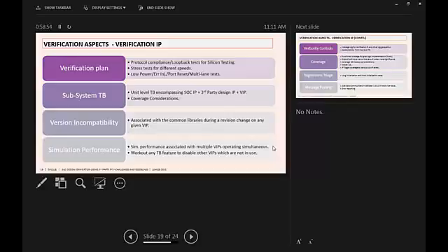When you get verification components from the same vendor, they come in a package, right? It's a VIP package, and it has PCIe, AMBA, SATA, and those things. Most of the time they use common libraries, so some of the ports and include packages will be there in both of them, and you will see issues when you try to compile.